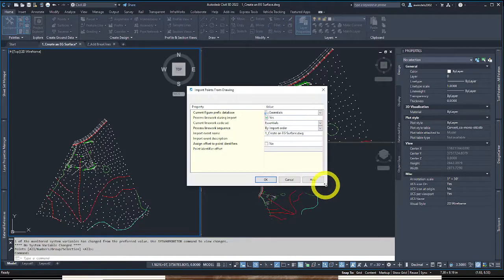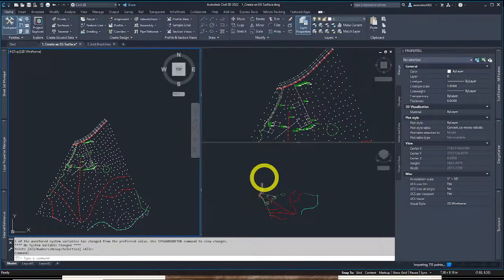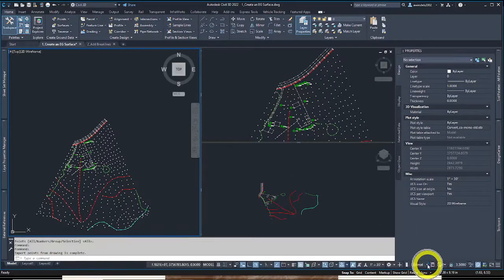This is going to bring in survey figures, but we need this to be showing. So if you have sample showing, you need essential showing. That's key here. Same with the line work code set. These two need to be the ones queued up. Also, yes to this. Process line work. These three are the biggies. Okay, it's going to go for a minute importing the points and processing the line work into the survey database. Give it a second, let the wheel spin.